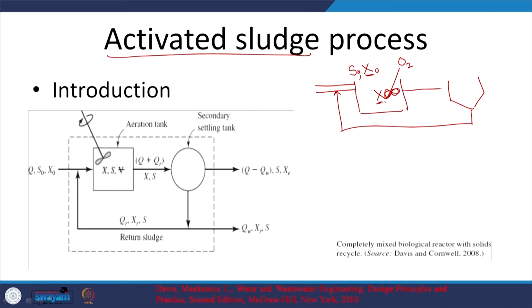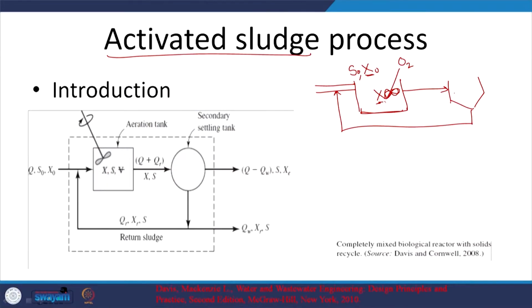Once we stop aeration, we send that to what is called a secondary clarifier or secondary sedimentation tank. What happens is, if we maintain the right conditions, the kind of bacteria that form here are what we call flock forming bacteria with some filamentous bacteria. We looked at this figure in the last session, where we looked at the microscopic pictures and saw the flocks being formed along a filamentous backbone. These flocks, or kinds of microbes, are going to settle down at the bottom. So, typically you can waste it,